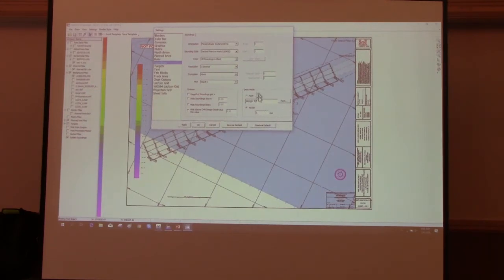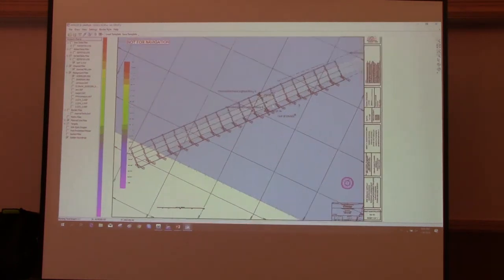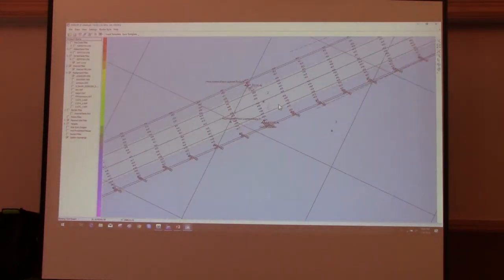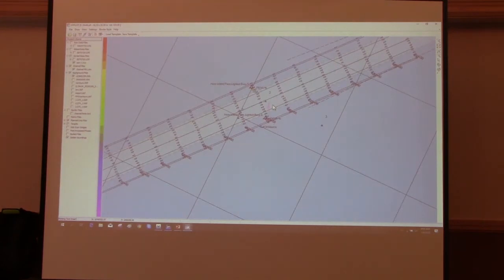You're pretty safe if you use this drawing mode here. You use vector for soundings, and you have the proper scale here, because with that it'll draw the actual soundings true to the scale of your chart. If you're using the fonts, I think that's where you could get into a little bit of trouble, because if you have a larger font, it's really hard to scale that properly to a sheet, especially exporting it out to a PDF. And some of these printer drivers react differently, also. So it's a little bit tough.